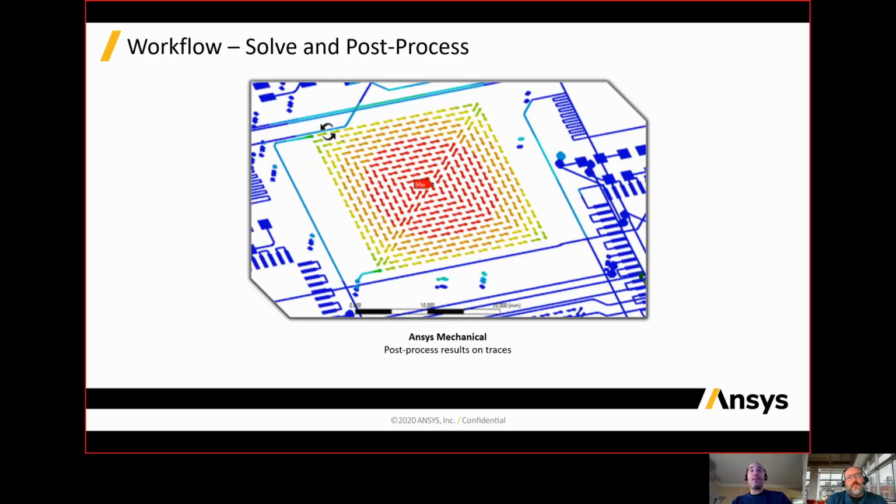The other side of it is anytime that you're trying to model a specific thing called hot tear that can happen to BGAs during reflow, especially secondary reflow when you do the other side of the board. And there's basically no other way to do it other than with reinforcement or with full 3D trace modeling. In full 3D trace modeling, you can maybe do it for 4 or 5 traces, vias, around the corner of the die.